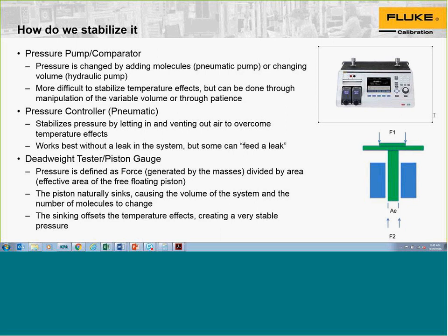Now the question is, you seldom see calibration people performing that test of going both up and down, especially on digital gauges. On digital gauges, the elastic element, or the sensing element, will be silicon. This is less likely to exhibit hysteresis, depending upon how it's packaged, as a metallic Bourdon tube is more likely to show hysteresis.